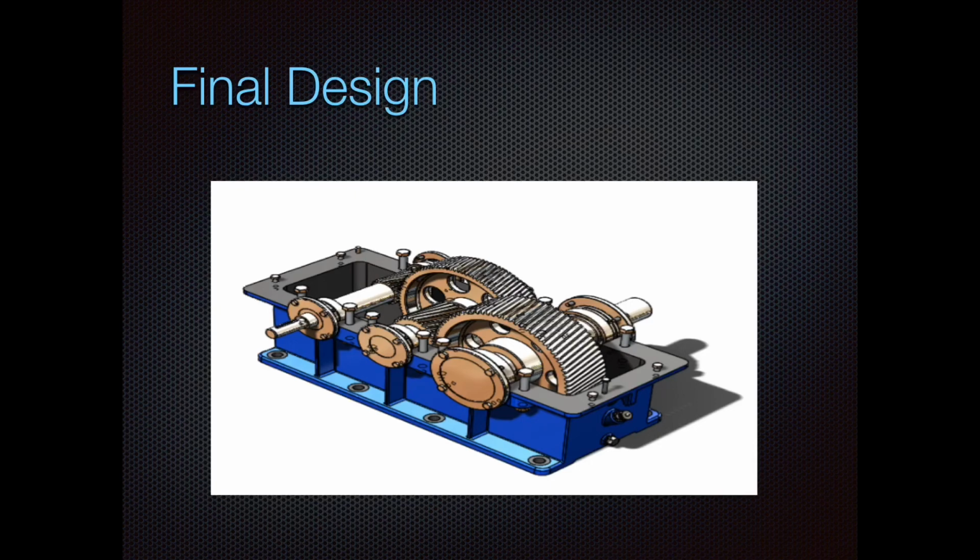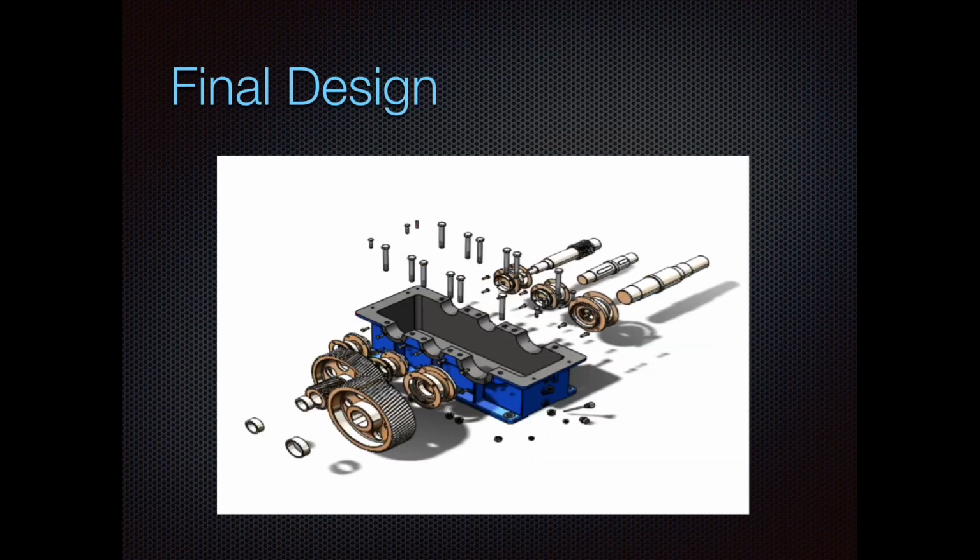An axial load of 150 newtons was applied as shown in the previous picture in the yellow region, and a downward force of 75% of the gearbox weight was applied, which was 1889.375 newtons.